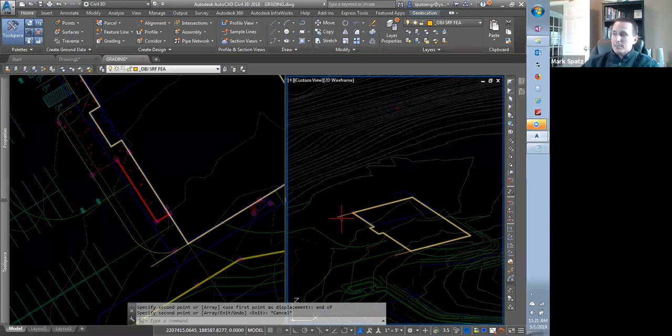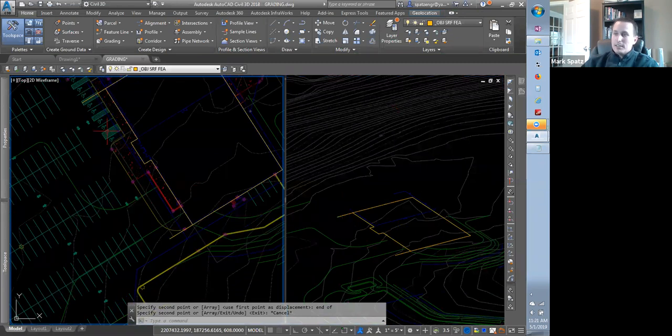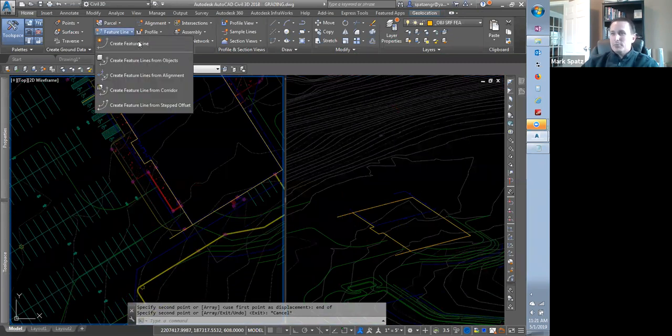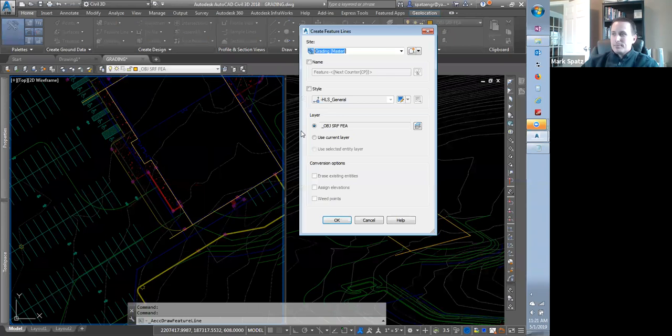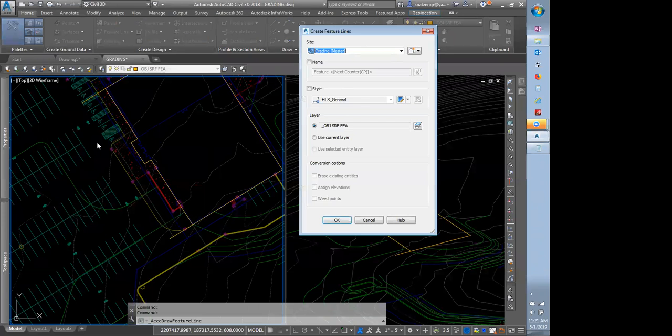They're starting at the same elevation, they're ending at the same. So then at that point, usually I would connect in between with the feature line. So I'm going to go back into my feature line command again. So go ahead and draw that grade -2%, copy it over to the next one, copy it over to the next corner like I showed here, and then let me know when you're at that spot. I don't want to keep zipping too far along.